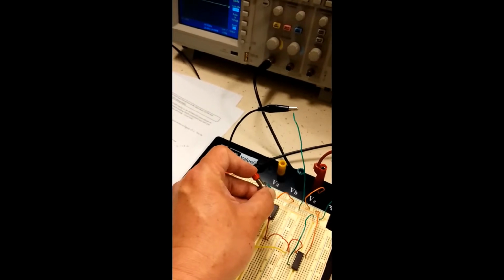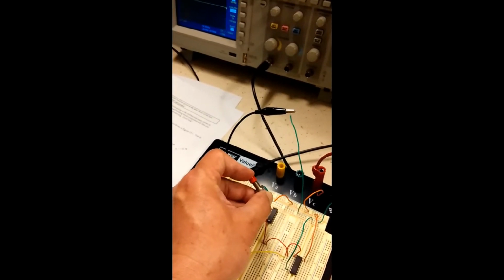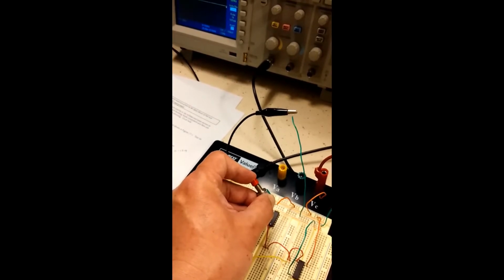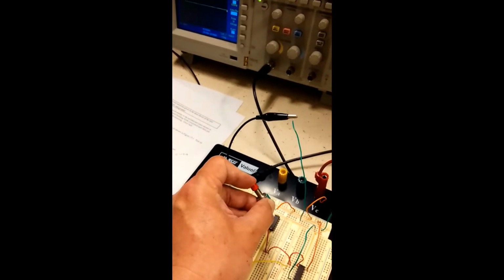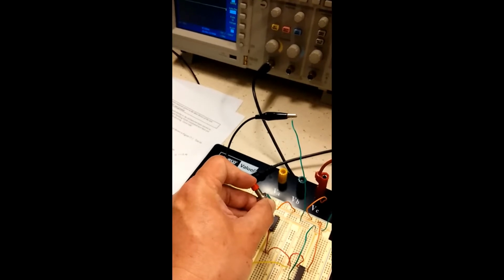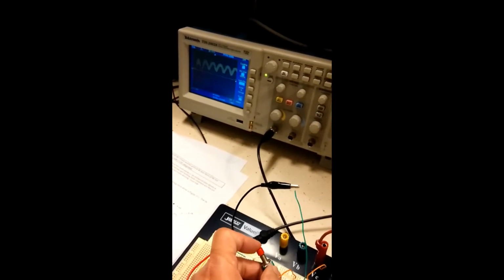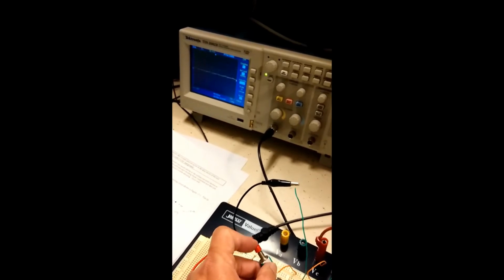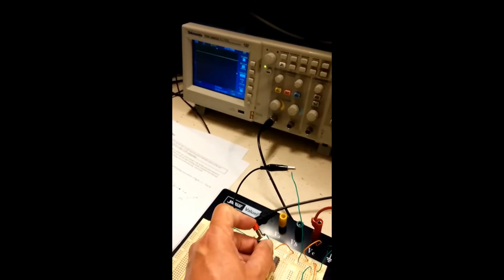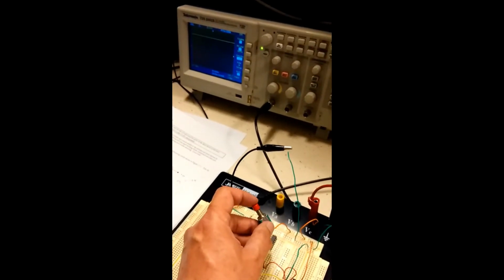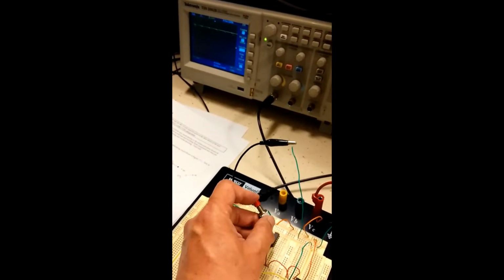So you have a high signal for both input A and B, and the NAND gate should have the output as 0. This is what you see, and you see the noise generated in this gate. So this is the problem with the 4011 when used with a mechanical switch.